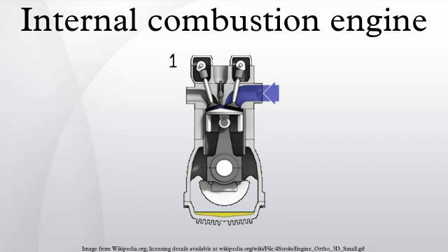Because here gas inlets and outlets are positioned at opposed ends of the cylinder, one can achieve uniflow scavenging, which, as in the four-stroke engine, is efficient over a wide range of engine speeds. Also the thermal efficiency is improved because of lack of cylinder heads. This design was used in the Junkers Jumo 205 diesel aircraft engine, using two crankshafts at either end of a single bank of cylinders, and most remarkably in the Napier Deltic diesel engines.